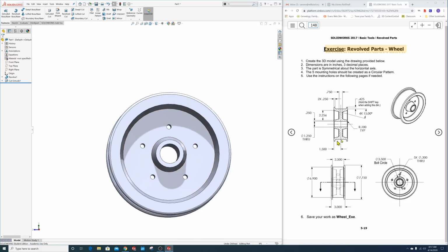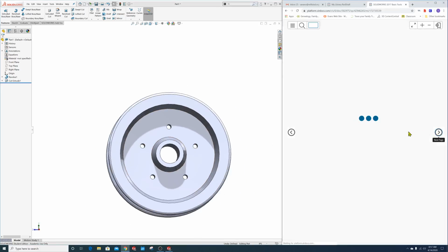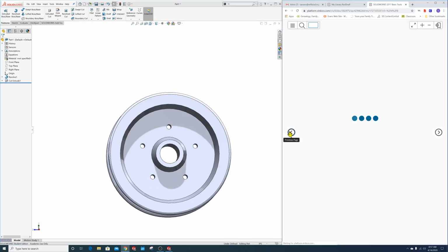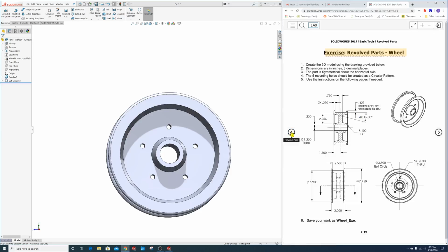Now, if you look at this, let's see what it tells you. Since this is a more advanced one, they expect you to go back and look at this, because some of you guys will miss this. If you just do it by this, you'll miss going back. And this is what I don't want you to miss. I don't want you to miss the fact that it says that it has a fillet with a radius of 1 typical. That means that all these edges should have a fillet with a radius of 1.